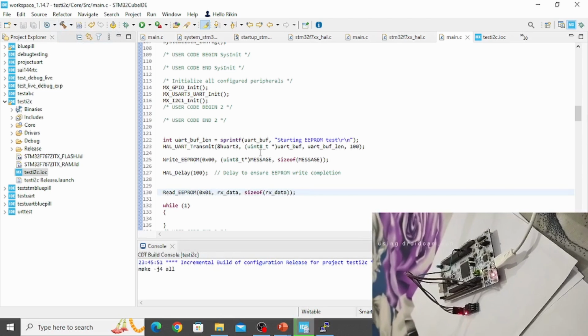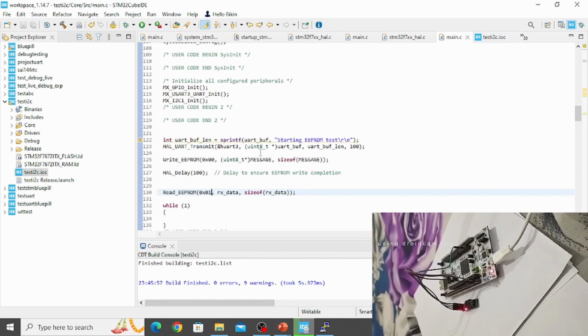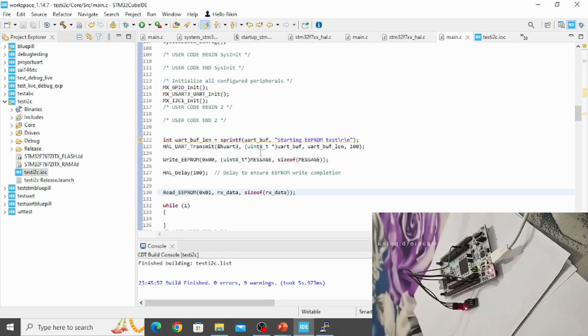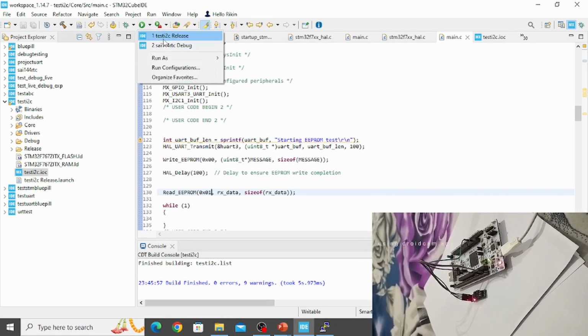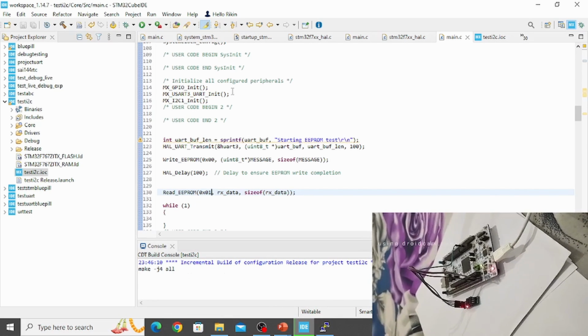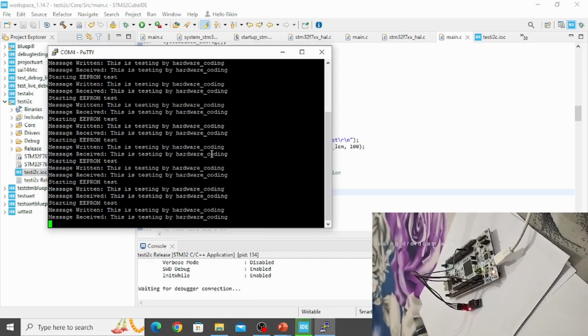As we discussed, now I am going to read the second row of the page. The first row would be the message's starting character, which is T, but now it should read from the second character, from H. So now let us upload the program on the hardware and check PuTTY.